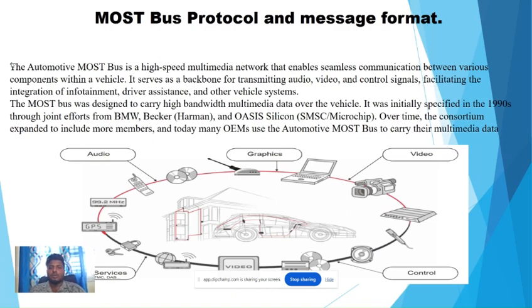MOST bus protocol and message format. The automotive MOST bus is a high-speed multimedia network that enables seamless communication between various components within the vehicle. It serves as a backbone for transmitting audio, video, and control signals, facilitating the integration of infotainment and other vehicle systems. The MOST bus was designed to carry high bandwidth multimedia data over the vehicle.